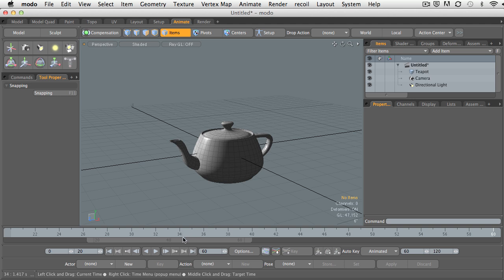Look immediately below our little timeline, our graph, and you're going to see this light gray bar. At the outside of this light gray bar, we have two little cubes, and these cubes are interactive, meaning that we can left-click and drag on them and interactively change the current start time and the current end time. So that's a handy little trick. Instead of having to add values here, you just left click and drag.